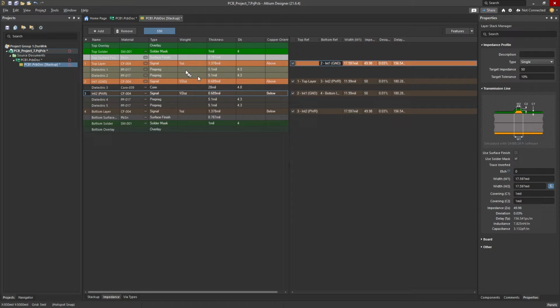And so now we have the Stackup where we can change the dimensions. We have the impedance layer, which identifies where the returns are located for each of the signal layers. And as we highlight each of the signal layers, all that information is automatically ported over to the user interface to the 2D field solver. So we're on layer 1, and that's microstrip, and so here's that geometry.